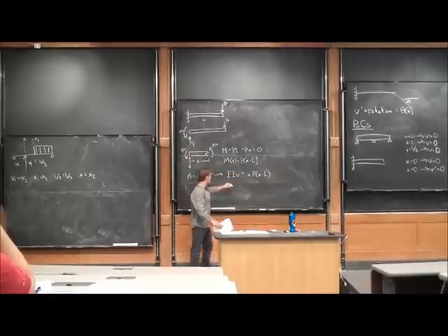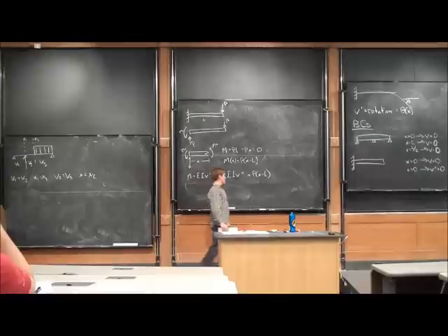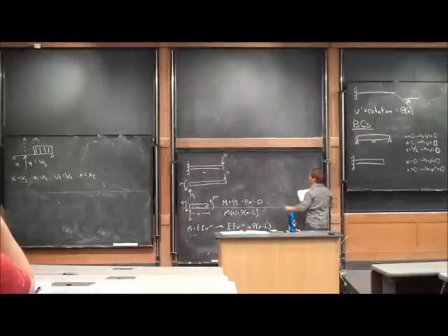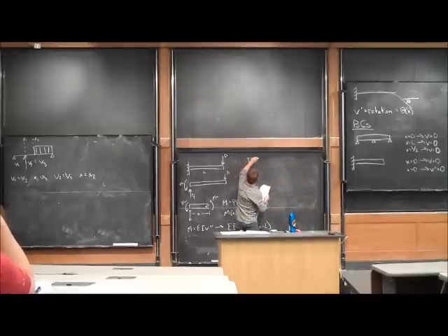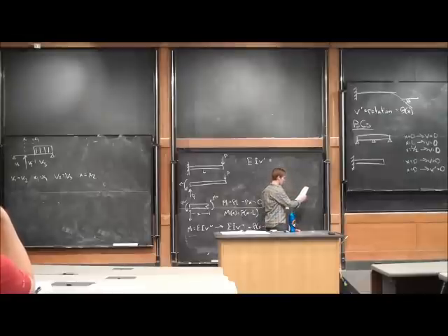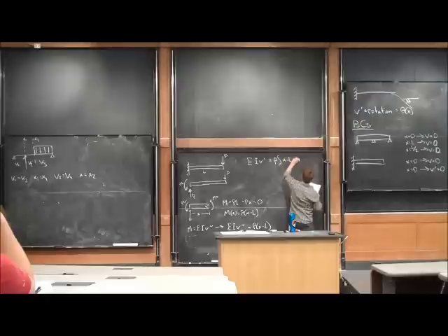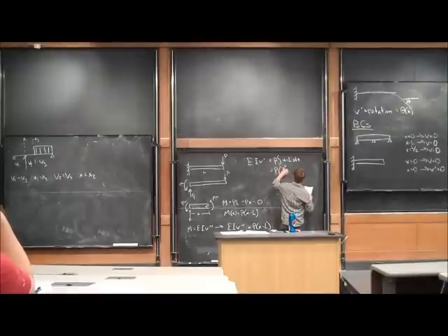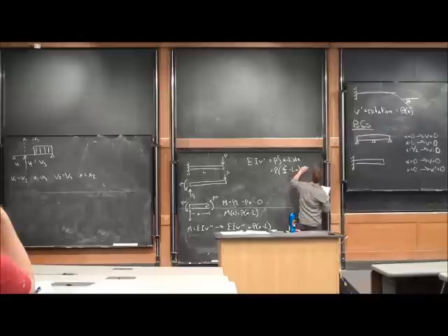So based on that, we can now solve for the deflection at every X location along the beam by integrating this equation twice. If we integrate it the first time, we can see that EIV prime is going to be equal to P times the integral of (X minus L) dx, which is going to be equal to P times (X squared over 2 minus LX) plus C1.